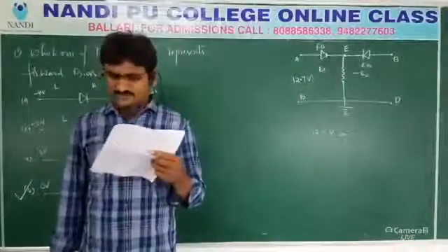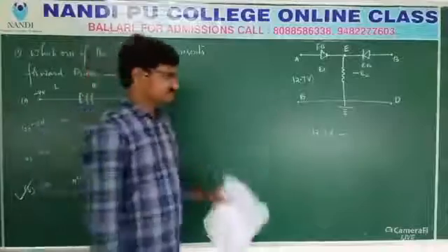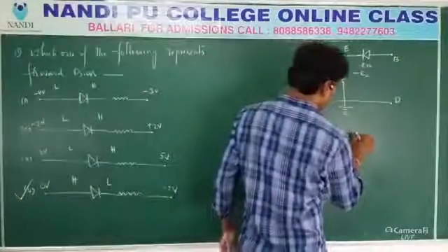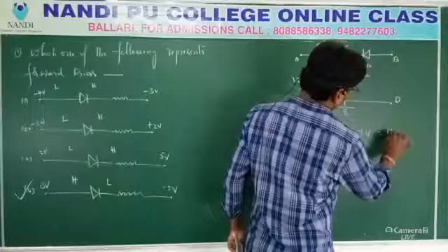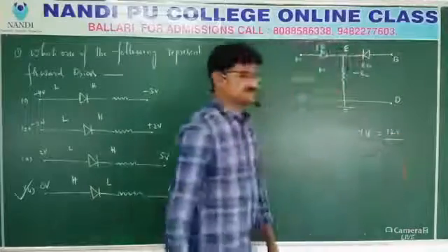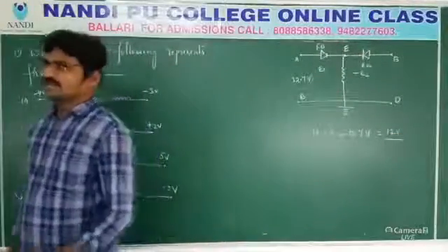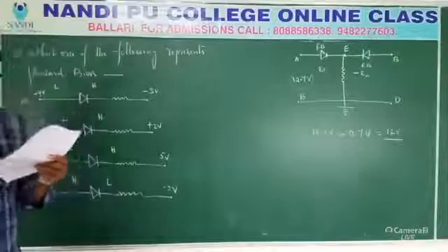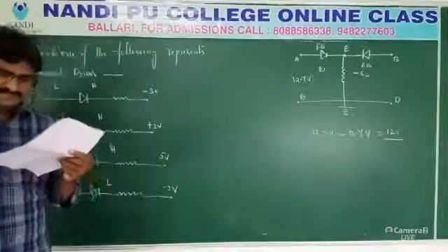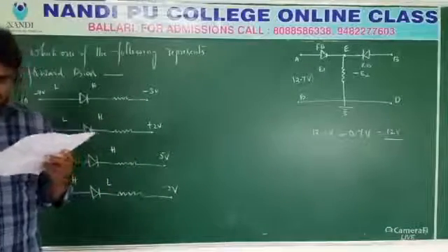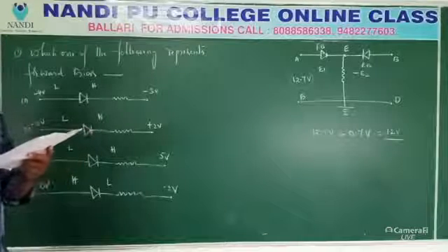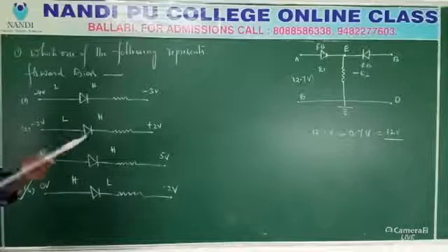So what is the second one's value? In each, the value is 0.7 volts. So what is your answer? It is 12 volts. Why? Because the input is given as 12.7, and the second one is reverse bias with 0.7 volts. So your answer is 12 volts.